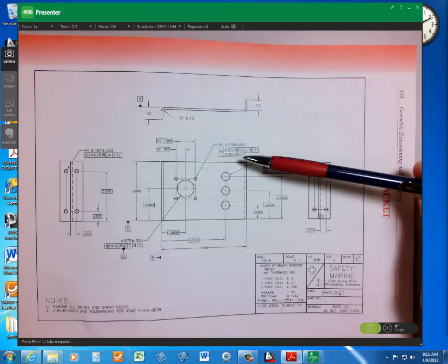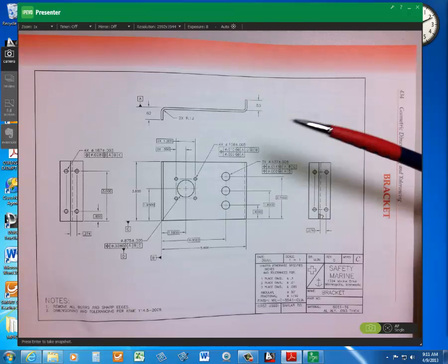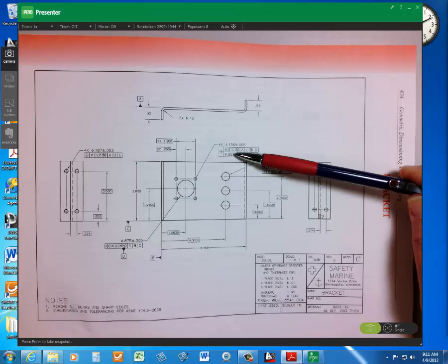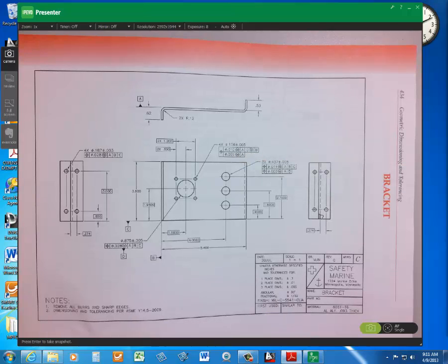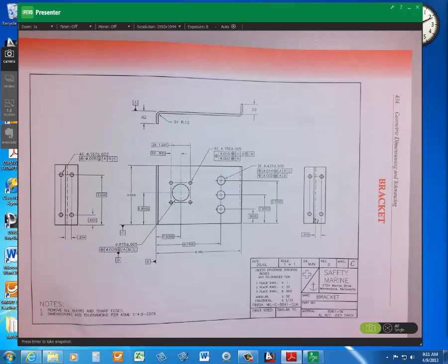So it's held in position. Each hole must be in position within the pattern at a 2 thousandths of an inch diameter tolerance zone at max material condition. Very tight control, a whole lot tighter than this. So the hole is allowed to fluctuate quite a bit, 14 thousandths off of axis. And the pattern of holes is allowed to be within 10 thousandths of that, but each hole has to be within 2 thousandths of that.